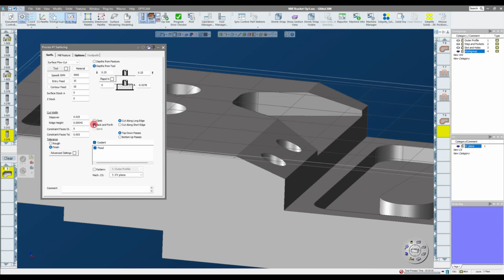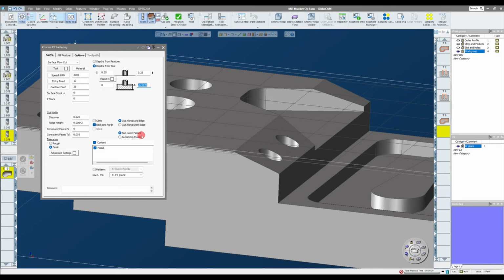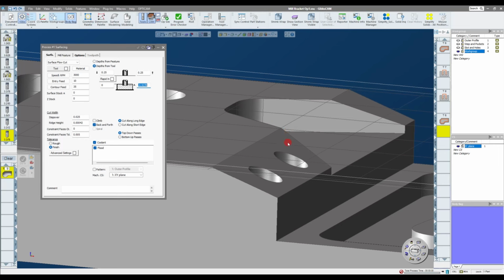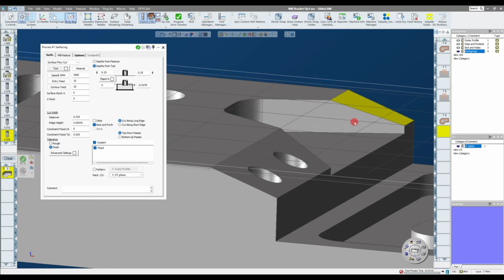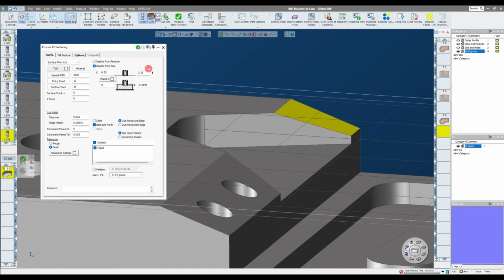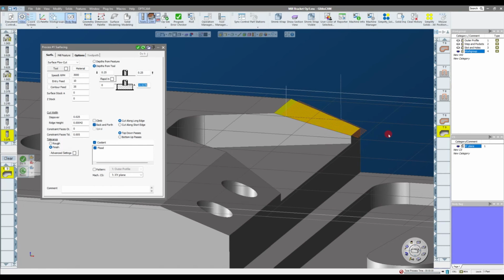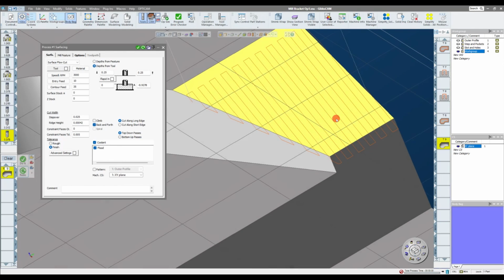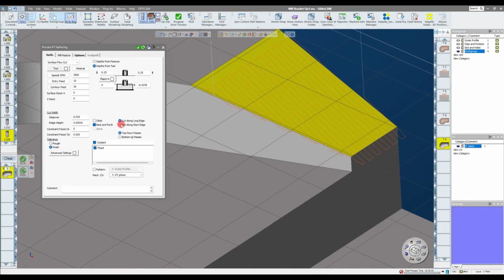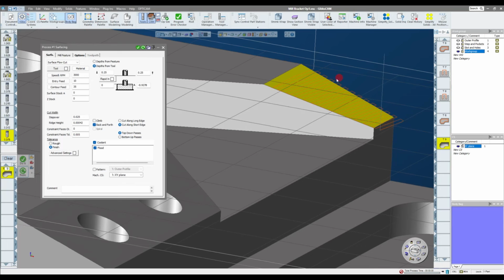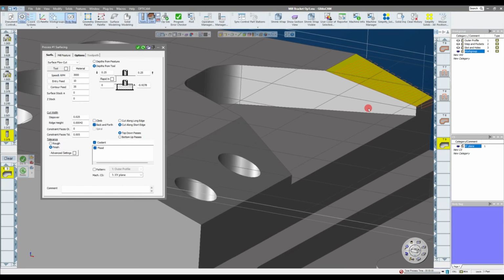We're going to cut it in a back and forth direction, long edge, and top down passes. Now you'll see I don't necessarily need to worry about these too much because it's going to use the face of the model as its top and bottom cut. So if I just select the face of the model and click do it, you see it gives me a zigzagging depth of cut. I'll cut along short edge, and it'll just zigzag back and forth the face of this part.